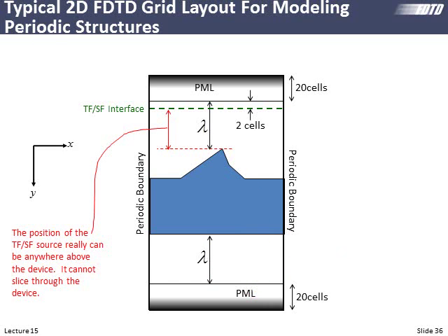And this is something we'll talk about in a following lecture, but very often we can get evanescent fields or temporarily guided modes in our devices that have these evanescent fields that come off. If those touch the PML, that's bad. That's bad because we won't be counting the evanescent fields as transmitted or reflected. However, the PMLs will couple to them, convert those into propagating waves in the PML, and essentially suck power out of your model. And that'll make sense later.